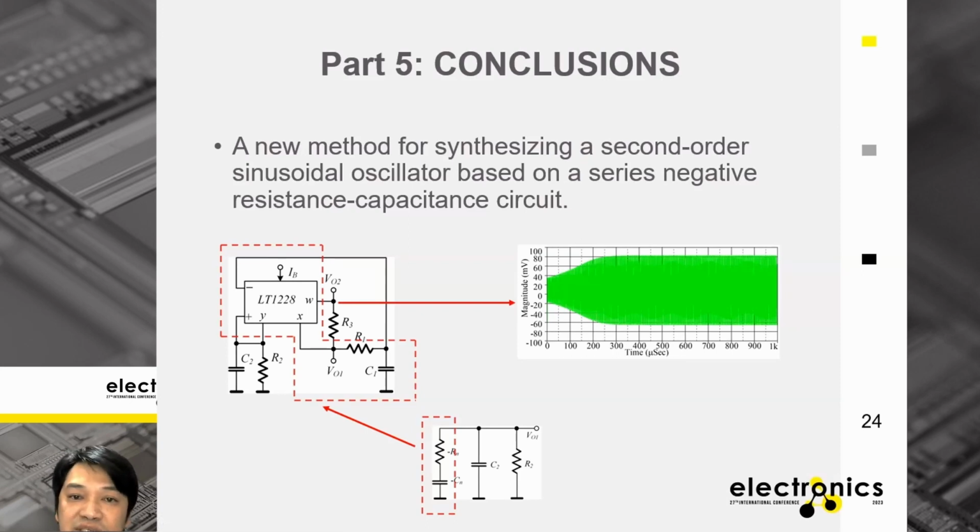The proposed simulator is electronically controllable, realized by a single LT1228 with R1 and C1. The sinusoidal oscillator is constructed by connecting R2 and C2 in parallel.